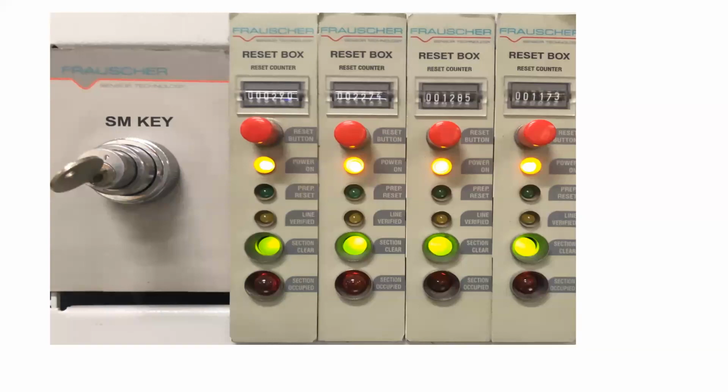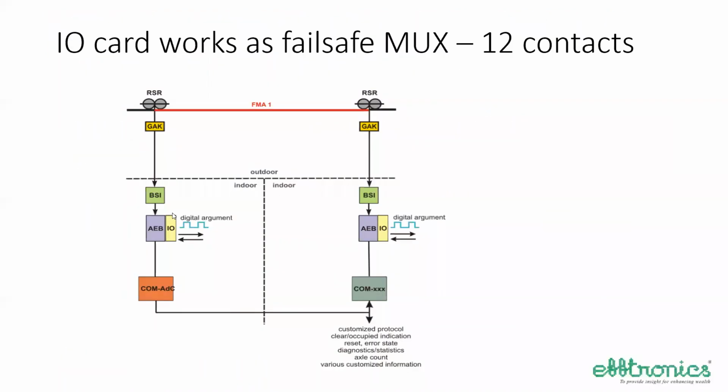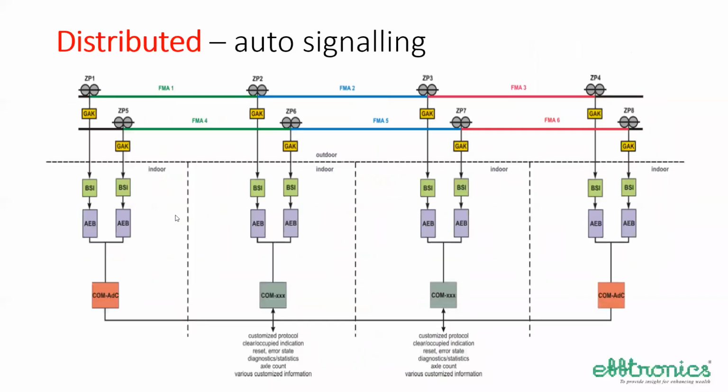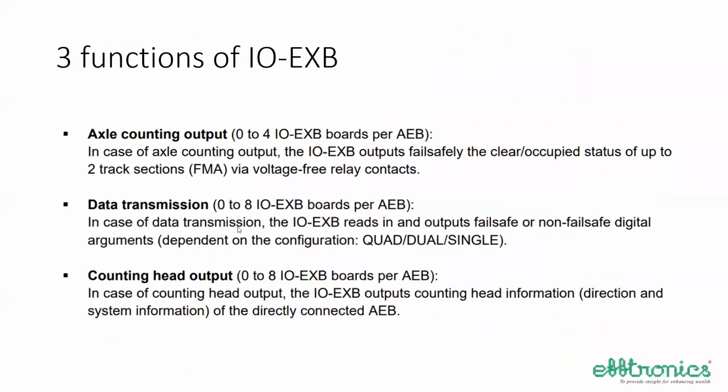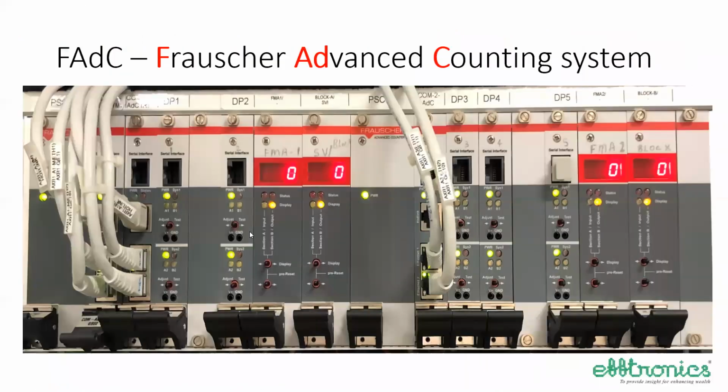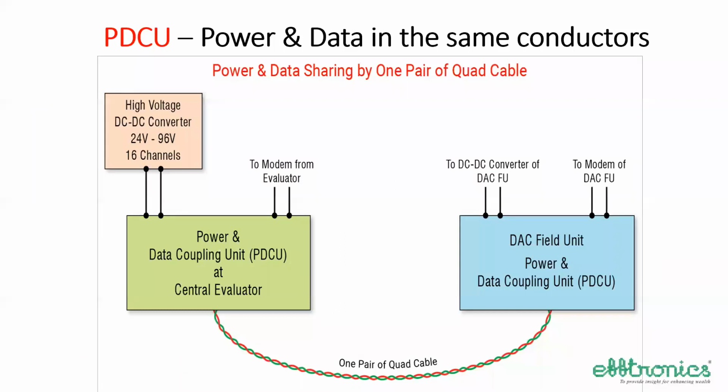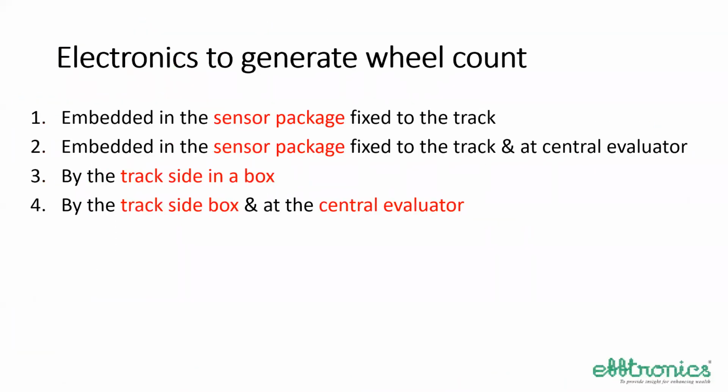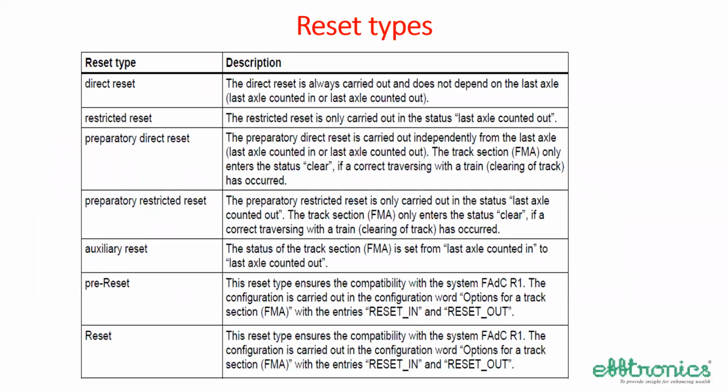Mr. Mohapatra has asked, is a separate relay rack required for EI, electronic interlocking? I think electronic interlocking should have a separate rack, sir. Am I right? Need not be actually. They are just the relays. It is a question of picking up of a relay with the potential free contact which is available inside. That can be kept anywhere. How does it matter? In fact, recently at one of the places, we said no relays are required.